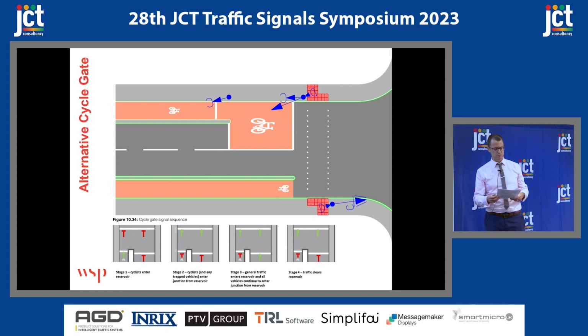My proposed layout enables the same, or at least similar, staging sequence to be used. When the rest of the junction is being served, the extra signal on the cycle lane is green, allowing the ASL waiting area to be accessed, replicating stage 1 of the cycle gate staging. Then the additional cycle signal goes red, and the early release starts, allowing the cyclists already in the ASL to leave, just as they did in stage 2 of the cycle gate staging. Then the main traffic signal goes green, allowing other traffic to progress through the ASL, just like stage 3.